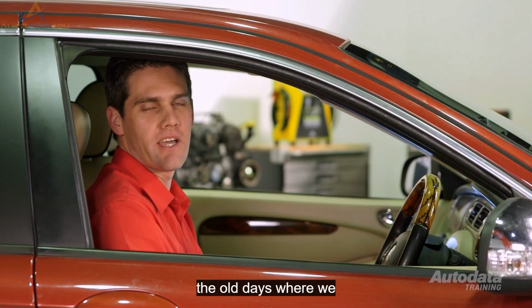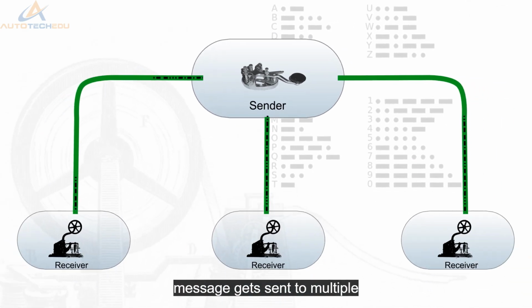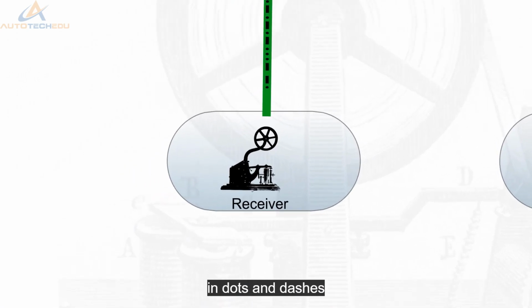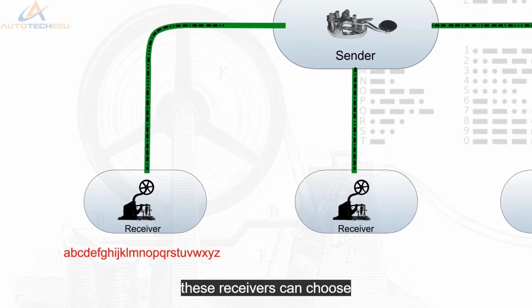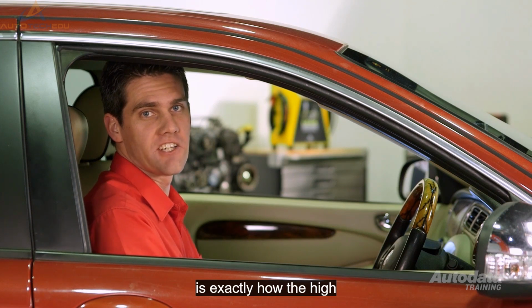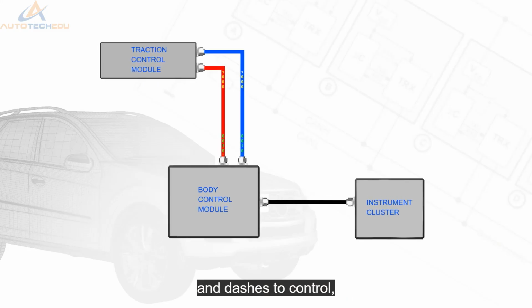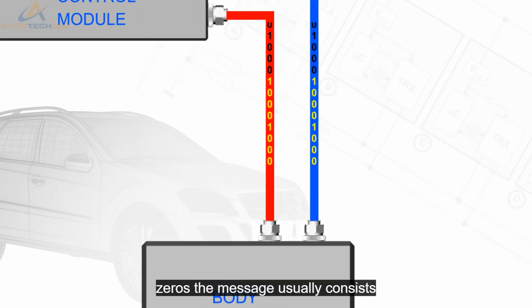Think of the old days where we had Morse code, where there is a sender and this message gets sent to multiple receivers. The message was received in dots and dashes, then converted into letters. These receivers can choose to ignore the message or receive it, depending on the current situation. This is exactly how the high-speed CAN works, but much faster, where instead of dots and dashes, the control unit looks for high and low voltages, or ones and zeros.